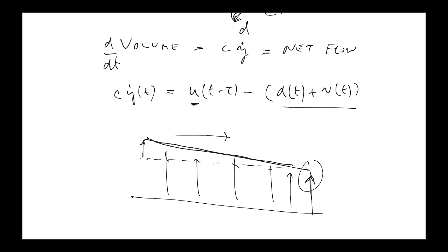In fact, the way we build these models is by doing system identification experiments, either by simulating these partial differential equation models that are non-linear hyperbolic PDEs, that account for conservation of mass and momentum, and then we fit parameter values that I'm not showing here, just to keep the model simple.